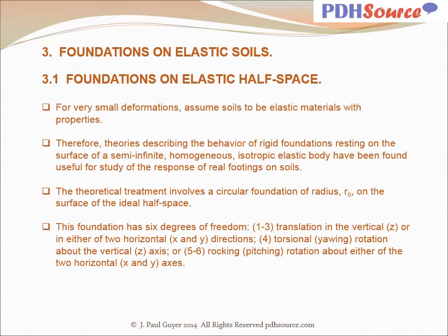With regard to foundations on elastic soils and foundations on elastic half space, for very small deformations, assume soils to be elastic materials with properties. Therefore, theories describing the behavior of rigid foundations resting on the surface of a semi-infinite homogeneous isotropic elastic body have been found useful for study of the response of real footings on soil.